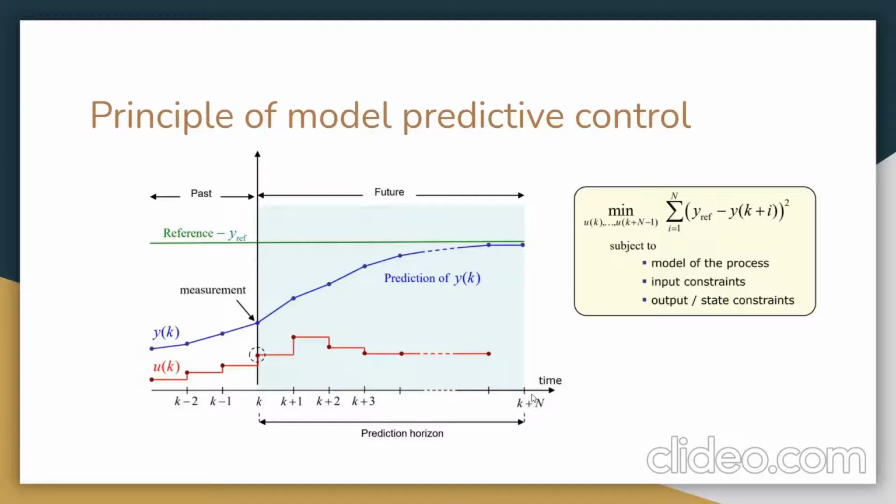It solves the problem and generates u_k, or control actions, that will drive the cost function towards the target, and also generates target states, or system states, that it expects to obtain by applying all of these controls.